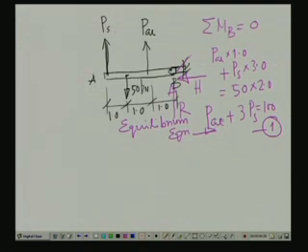Now, if we look into the deformation of this member, this particular bar AB is a rigid one. Since it is subjected to a load of 50 kilonewton, it will undergo a movement in a circular path, considering point B as the center. Since the deformation is small, we approximate this circular arc as a straight line, and we join this line.